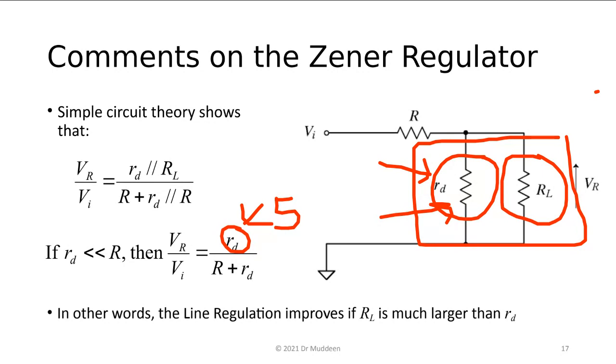Right, always remember there's a reason that we're talking about these things. There are reasons that manufacturers give you data like the diode on resistance. Why? Because it determines what you could put the diode regulator on. They give you things like power dissipation. Why? Because it determines how much current they can pass through the Zener diode without burning it. In the case of the capacitor, the working voltage: how much voltage can I put before the capacitor fails? In the case of the rectifier diodes, the PIV value: how much reverse bias, or inverse voltage, can I put on the diode before it will fail.